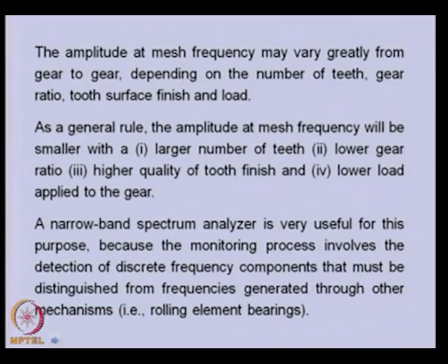The amplitude of mesh frequency may vary greatly from gear to gear depending upon the number of teeth, gear ratio, tooth surface finish and load. As a general rule, the amplitude of mesh frequency will be smaller with a larger number of teeth, lower gear ratio, high quality of gear finish and lower load applied to the gear.